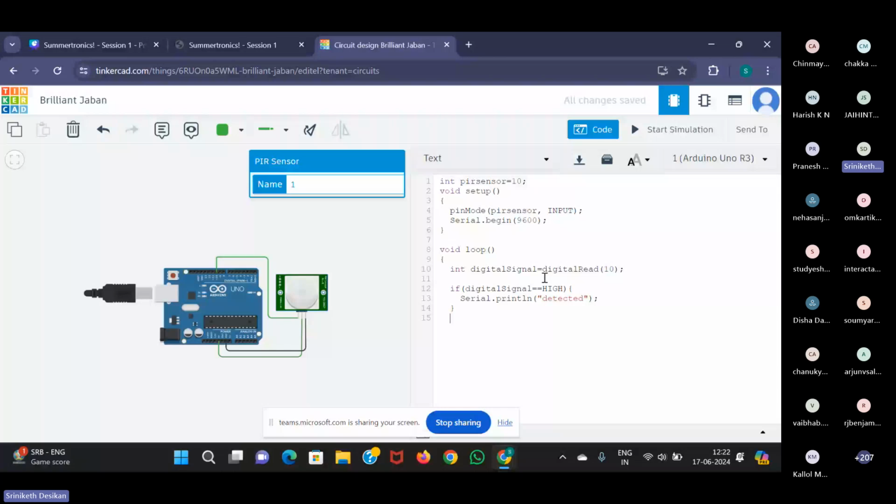I'm going to go ahead and introduce a delay of 2 seconds here. I hope you remember this 2000 is because the delay parameter accepts the input in, sorry, milliseconds. I'm very sorry. It's in milliseconds. So I need to give 2000 to introduce a delay of 2 seconds. So that really completes this program.